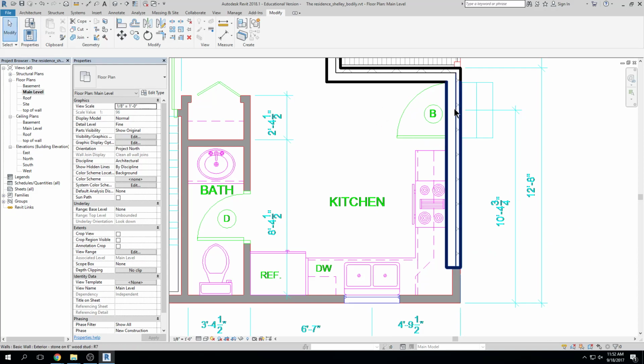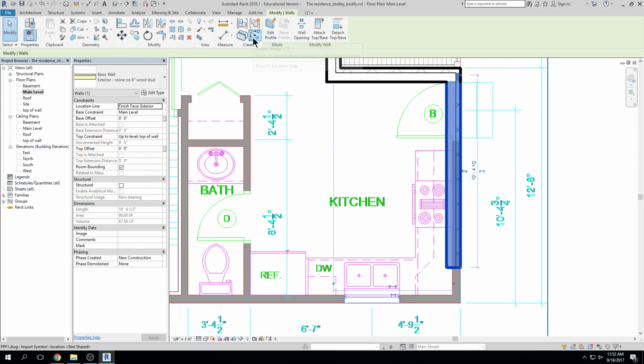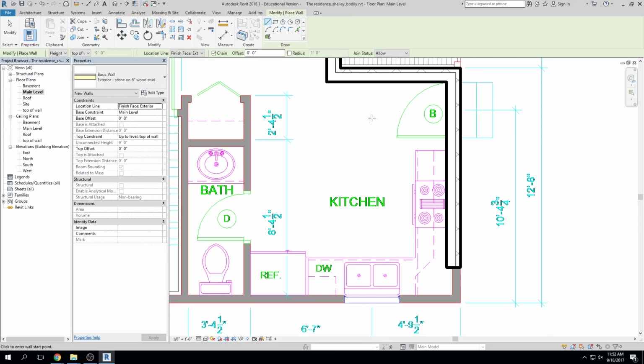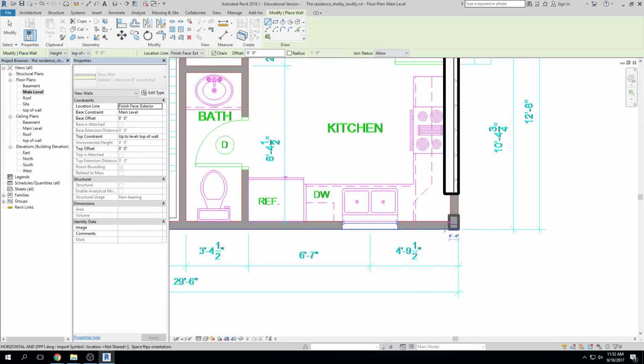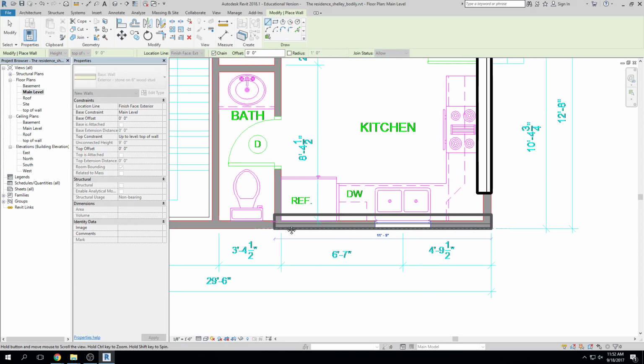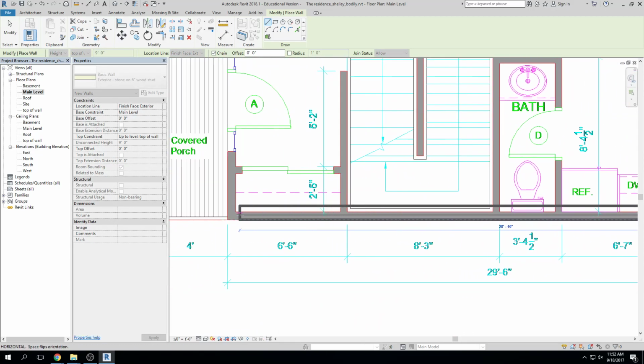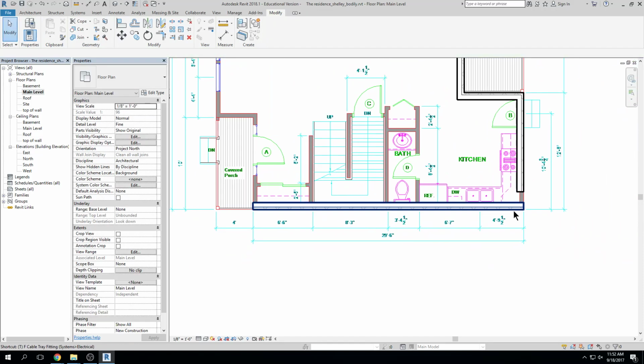Okay, I click on that wall, make similar, and I keep going. Now, you're thinking, wait a minute, there's a gap there, right? I'm going to come back to that. So trim, TR, click, and that trims it up.